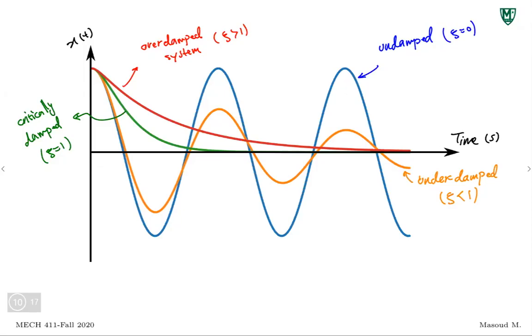We'll see later that I'll talk about dampers in series and parallel. Well, same situation we had with spring mass systems. Right? We simplify every system into the general form of the equation of motion, m x double dot plus c x dot plus k x, and find the equivalent of mass, stiffness, and damper, and use that to study the system, because now we know the system response and the solution to that equation of motion. That's why, again, we start from very simple systems.